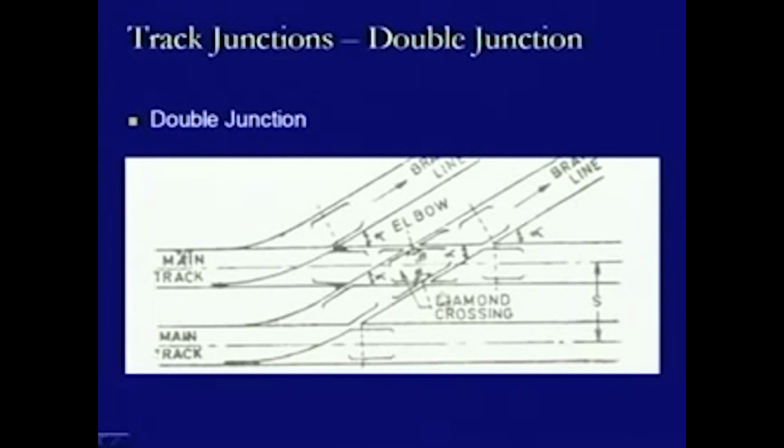So, therefore, whatever accessories or whatever type of crossings need to be provided on a diamond crossing, that is two pairs of acute angle crossings and two pairs of obtuse angle crossings, need to be provided in a diamond crossing. So, this is acute angle, this is acute angle, this is obtuse angle, and this is obtuse angle. We have a switch here, we have a switch here, and that is how they are operated. And this is another location where a crossing will be there, or there is one crossing which is provided at this location. There are two extra locations where two more crossings will be there.